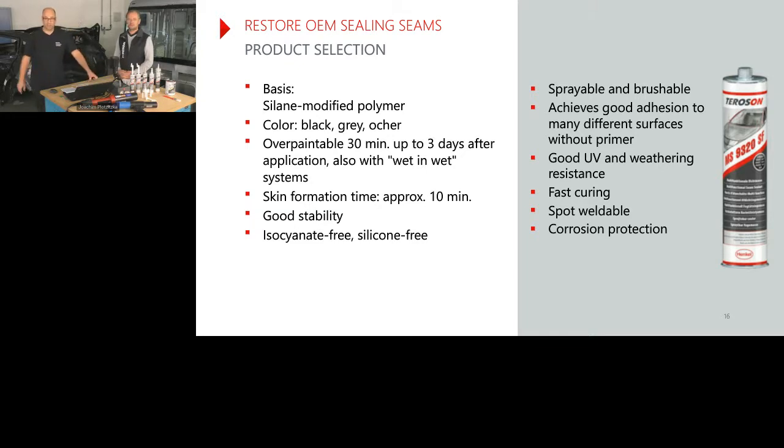So we'll be happy, yeah? Fast curing and spot weldable as well. So some people use this product between the flanges. So you apply it, put the panel on top, and then you make the spot weld through the panels. You squeeze away the product, and then you can have electrical contact and make the spot weld. So is there a certain time when you have to do this? You should do it before it cures. Otherwise, as long as it's liquid, you can make it.